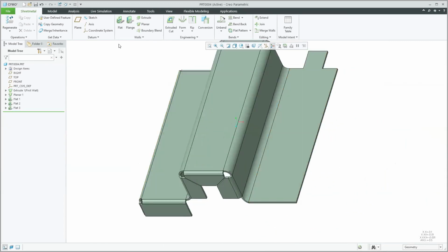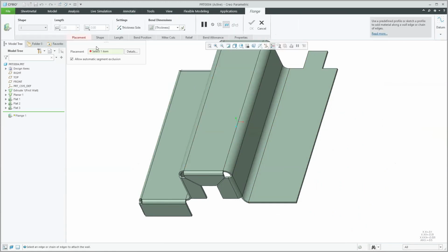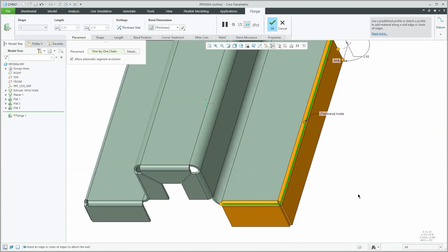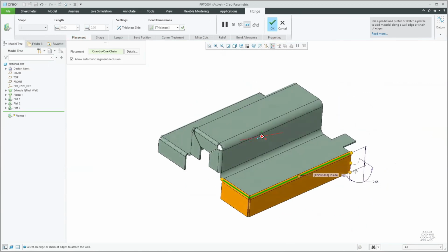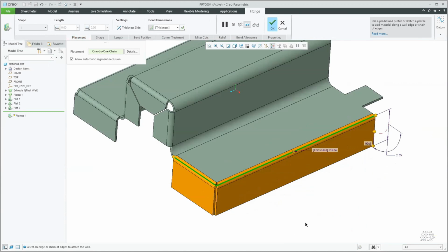Now let's do a flange wall. With the flange wall, again, you can hit the button. You've got the different shapes over here, so very similar. I'm just going to start with the I wall. If I pick this edge right here, and don't use control, use shift, you can pick the next edge that you want to add, and it's going to add on to that. Again, I can't pick an unconnected edge. That won't work. And that's going to start to create the wall.